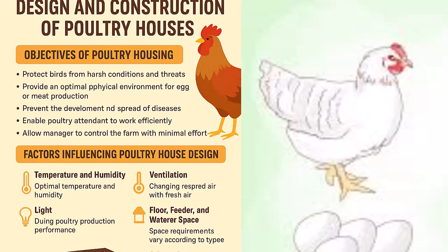A poultry farmer in Upper Egypt built a 45-foot wide east-facing open-side house for 10,000 broilers. After 2 months, mortality increased and birds showed heat stress. Identify the possible design errors and suggest modifications.